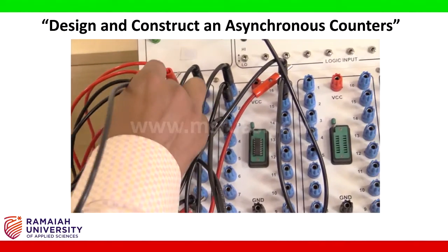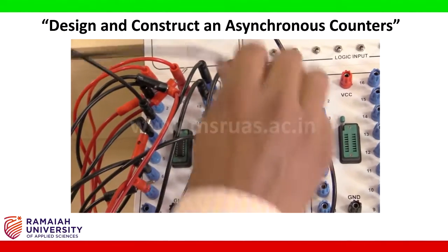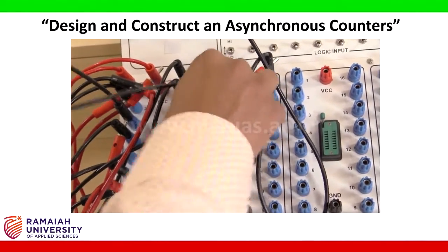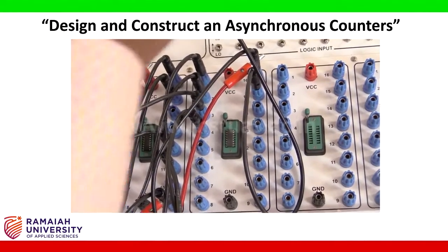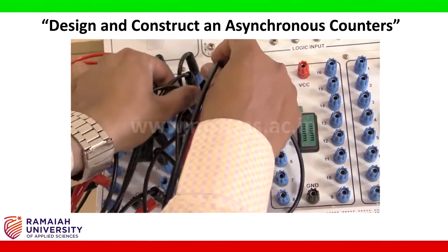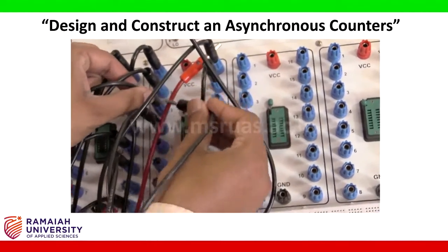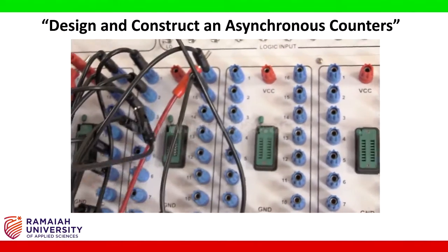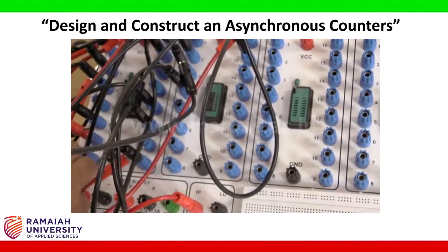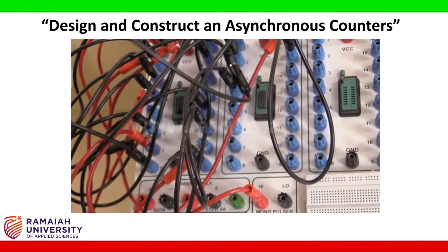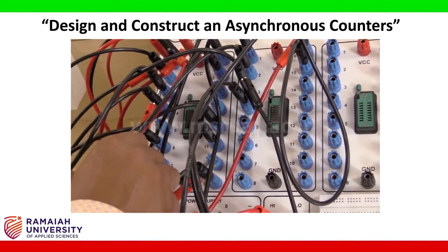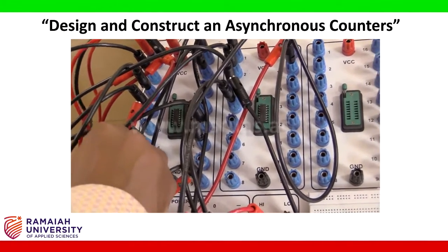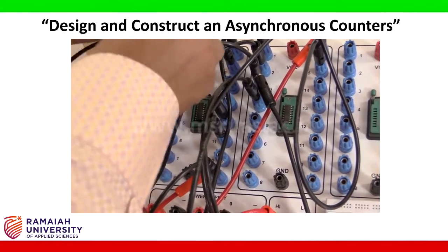Pin number 3 of the first IC base and pin number 3 of the second IC base are shorted. From that, pin number 8 of the first IC base is shorted. So from there it is going to VCC. So I will connect here.